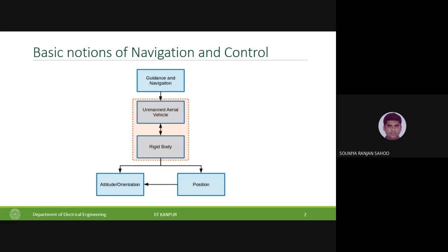Once you have some path planning algorithm in place, it essentially gives you the X, the Y, the Z, basically the entire translational path or the point in three-dimensional space. Along with that, it gives you the heading, or the yaw angle that you're supposed to maintain. In a conventional quad, you cannot independently specify the roll and pitch angles independent of the XY motion, the motion in the horizontal plane. So the commands are only these four quantities: X, Y, Z, and the orientation angle psi.